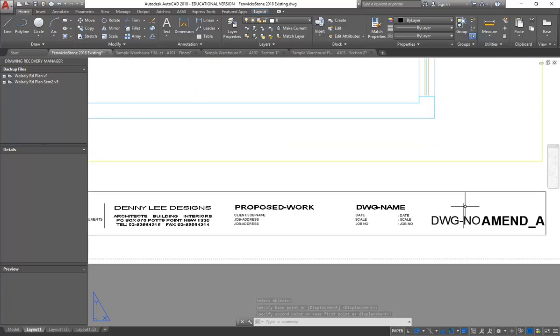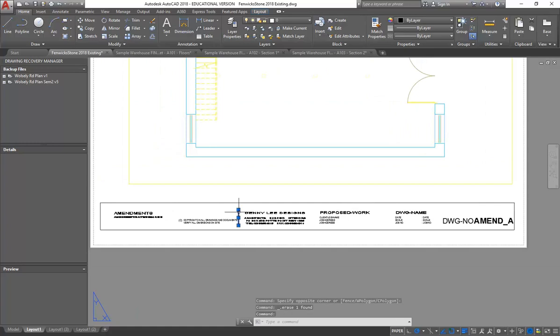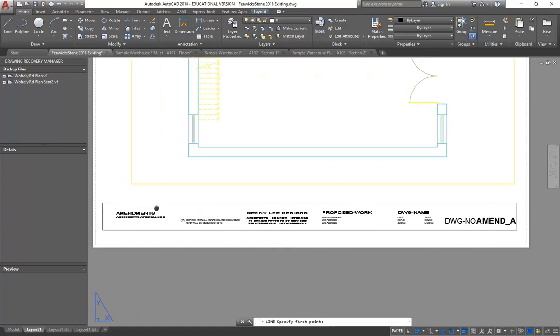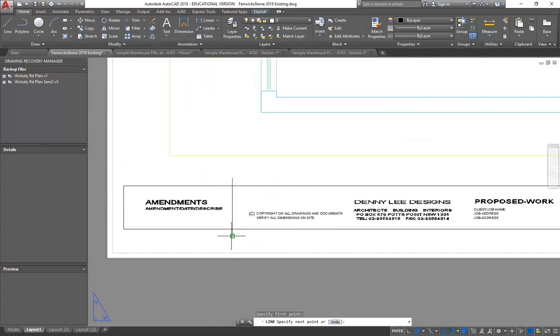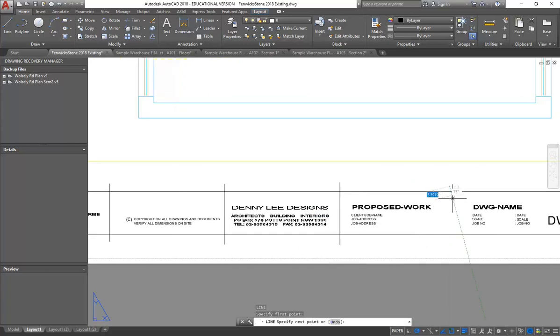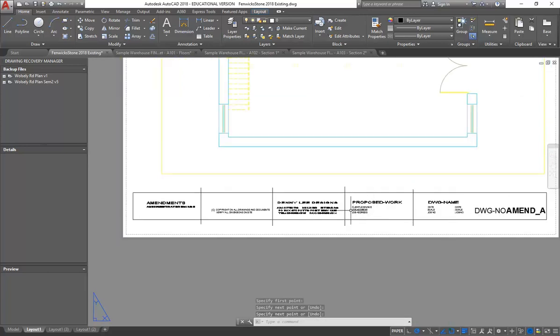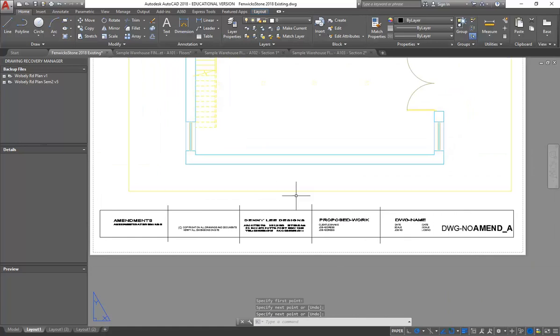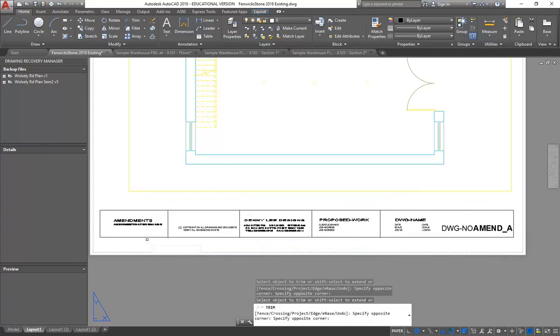Okay, so that way, without making attributes, you can use attributes that have already been made to make your own title block. And it's an important thing that you need to be able to do. So I'll give you a little while just to try and set up your title block with, at least with new lines. You don't need to do new attributes or anything like that. But again, make sure you find an odd title block that you can explode and modify.